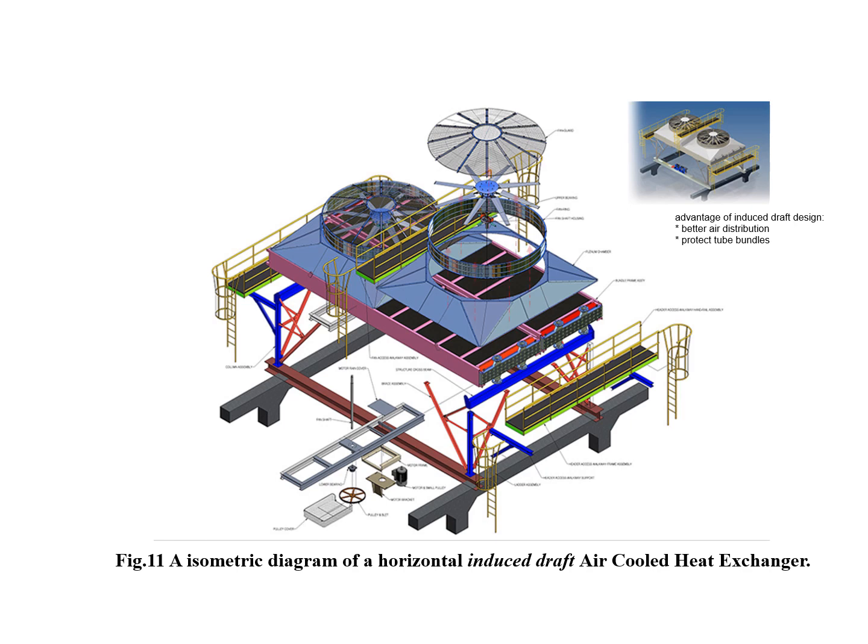However, when the temperature of the discharge airstream is higher than 95 degrees Celsius, forced draft designs should be considered. This is because the high temperature air out of bundles may cause potential damage to fan brace bearings and other components which are in the path of the airstream.